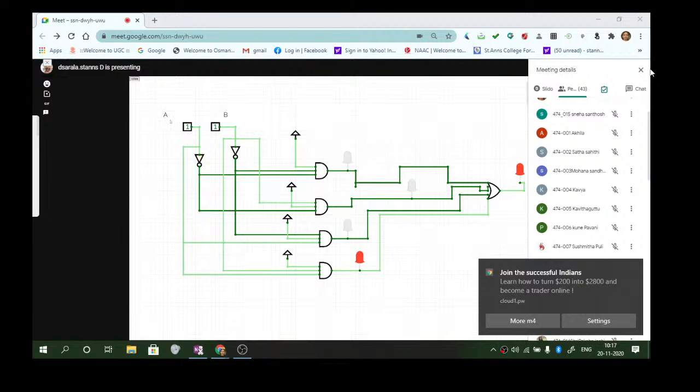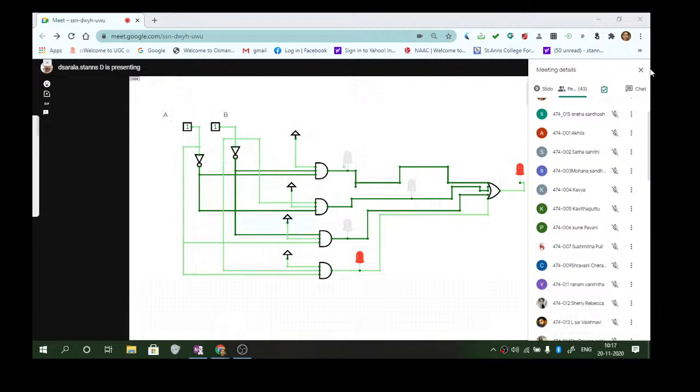Next, they are connected by means of an inverter. So when 1, 1 is taken, this becomes 0 and 0, right? So for 0 and 0, this line is selected and you will get the information from this. For 0, 1, this line is selected; for 1, 0, this line is selected, and so on. So now let me show you the actual operation of the circuit.